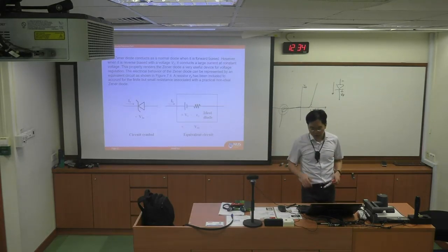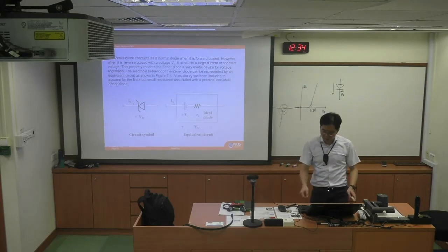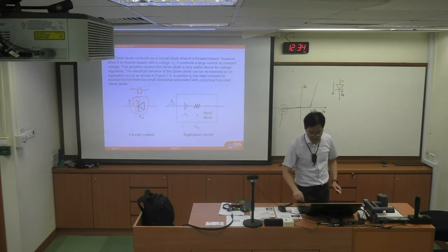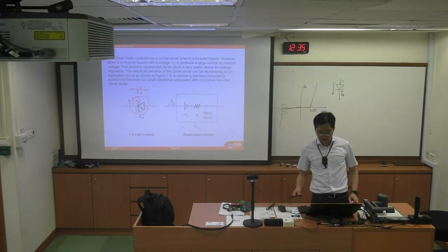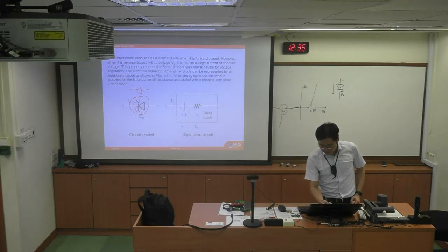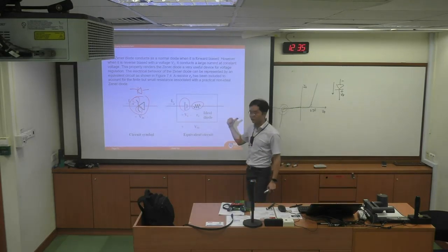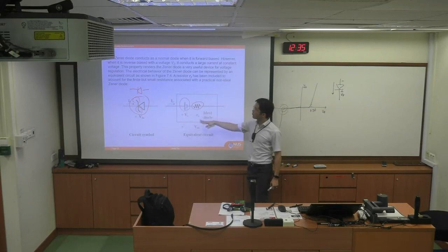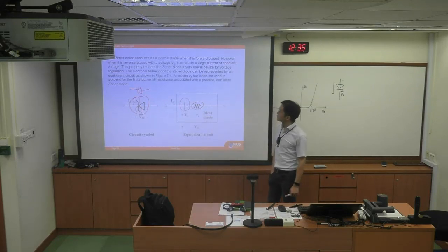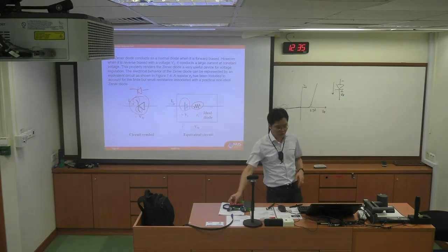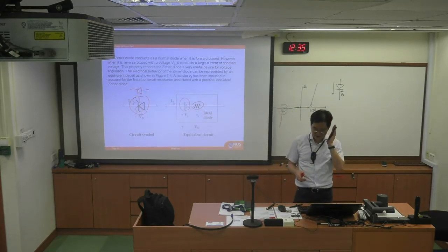Now, why is it important? By the way, the Zener diode compared to the regular diode is denoted by this sign. You can see there's a small slanted symbol over there. And this can be modeled as the reverse bias Zener diode breakdown voltage plus the series resistance at that moment when it flows the reverse current. Right? That's how you're going to show it. And that's a resistor RZ, which plays a role in the voltage regulation. We'll be coming to that in the coming slide.